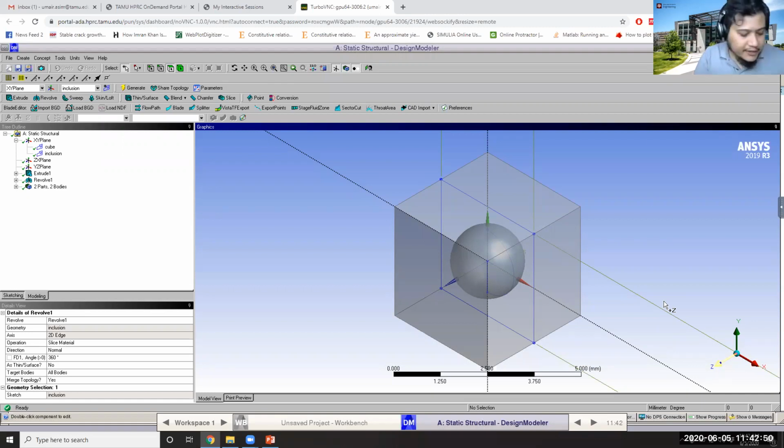You'll encounter some cases where you don't have symmetry in either the geometry or in the material. For example, I guess Hamza was the one who asked about the grains. If you are talking about a granular level, assuming a titanium grain, titanium has an HCP crystal structure and it is highly anisotropic. I strongly suggest you not make use of the symmetry, because it is not real. Although you will have a geometric symmetry, the material behavior is not symmetric. So I urge you not to use it in those kinds of cases.